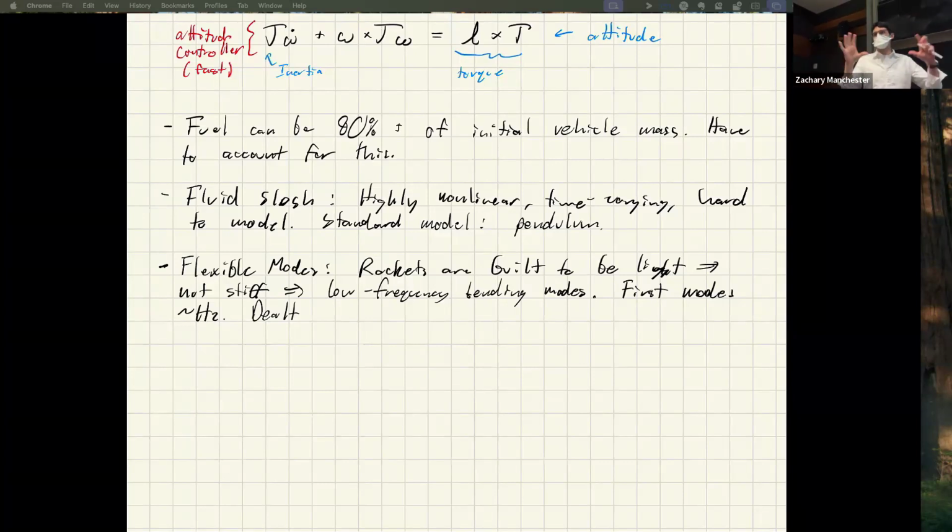But it fits into your manipulator dynamics. So you would model that in your dynamics and you'd have an explicit set of states associated with each mode. And then you can just put heavy penalties on those in the controller, in your Q matrix, such that the controller won't excite those, right? So that would be the model-based way to do it.